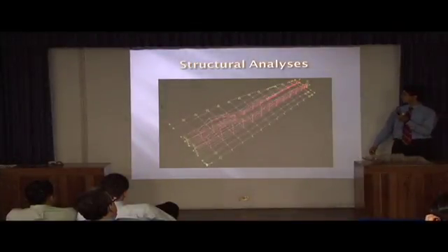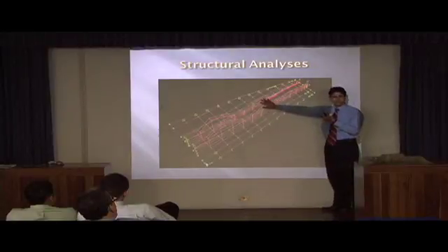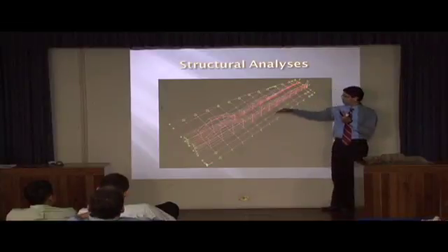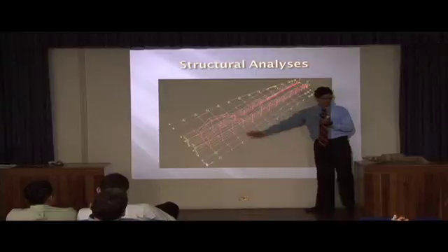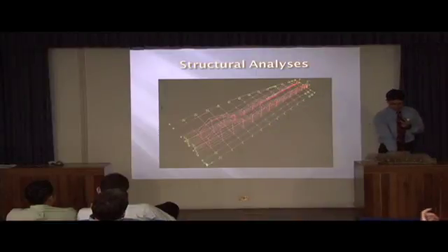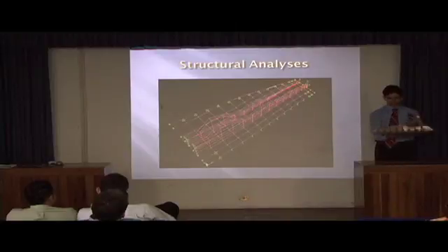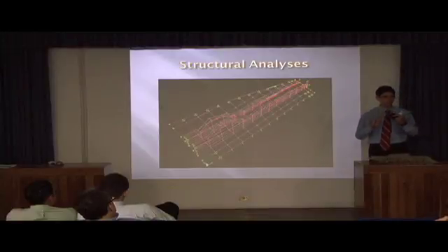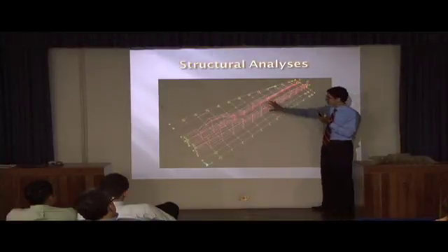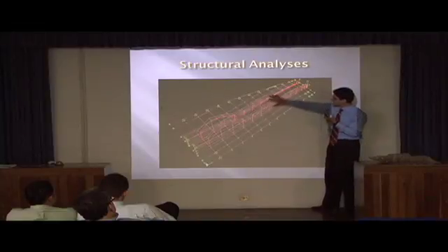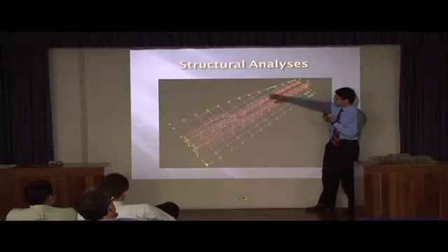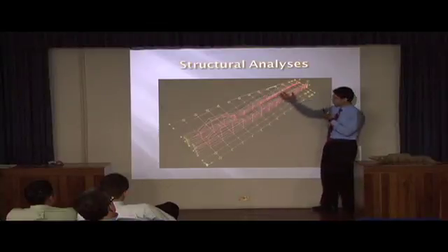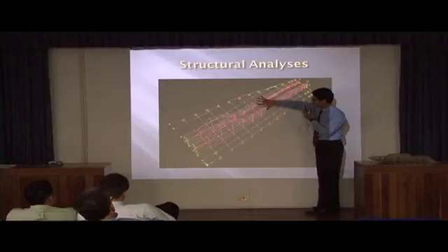Now the structural analysis. We can see the gray lines are the original form. Then, if we put some loads here, they will have a new shape. The deformed shapes are represented in the red lines. So, imagine if we put some loads on the top of this, it could be like a structure that tries to bend, forming a kind of smiling beam. So that is a similar behavior. In this case, the loads are here and here, because here we have the engine and reduction gear, and here we have the generators. So it will be like a beam, and this will try to bend.